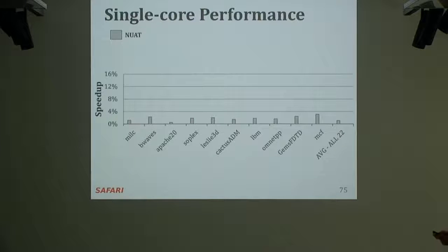So there's actually prior work that had this idea. This is an HPCA paper, I think, from 2014, I don't remember exactly. What it does is, after you refresh a row, if you have an access to it coming soon after, you can access that row faster. So it's partly the ChargeCache idea, but it uses just refreshes. As I said, refreshes are really asynchronous with program accesses, so it's hard to think that you'll be accessing a row that was recently refreshed with high probability.